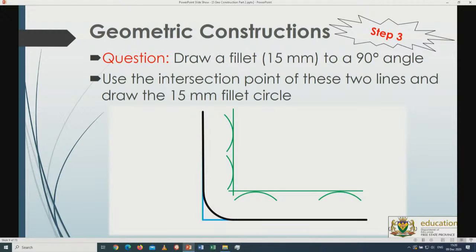Now just take a look at the quality that I'm talking about. The final product must be an A line, and we used to say it's the black lines in PowerPoint, but also the dark thick lines. And then the construction lines, those are the green lines. In other words, if you're an arm length away from the drawing itself, it means that you must struggle to see those lines. It must be very light. Use the weight of the pencil in drawing those lines.